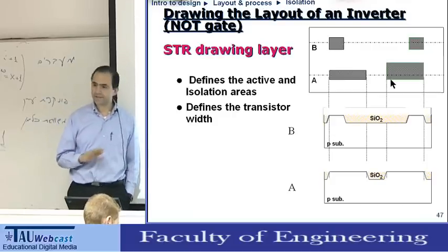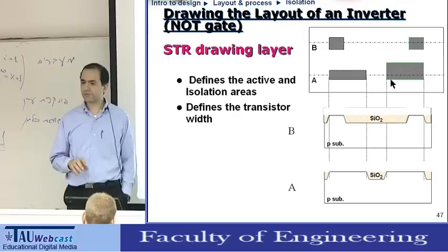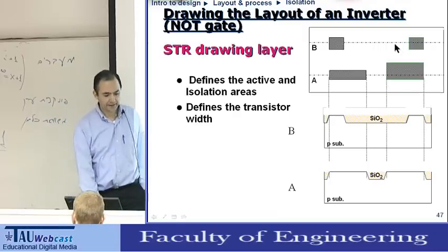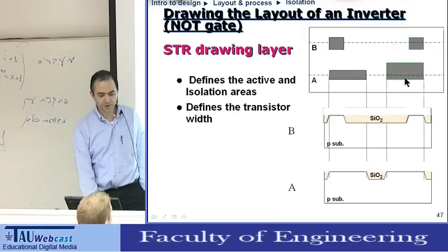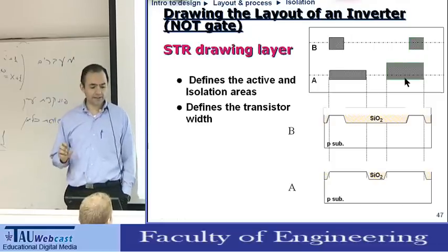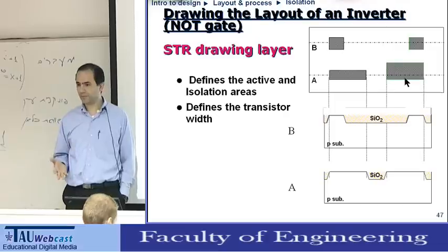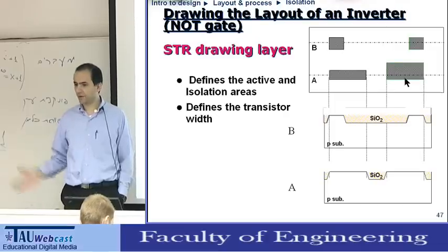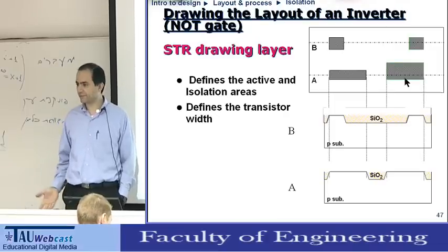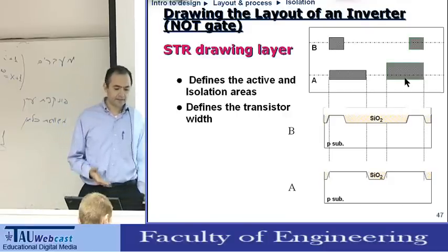And then we'll put resist on the wafer, and we'll expose through the mask. The areas covered here with chrome will not get exposed, and the areas that will get exposed will eventually develop, okay, and go away. That is positive resist.